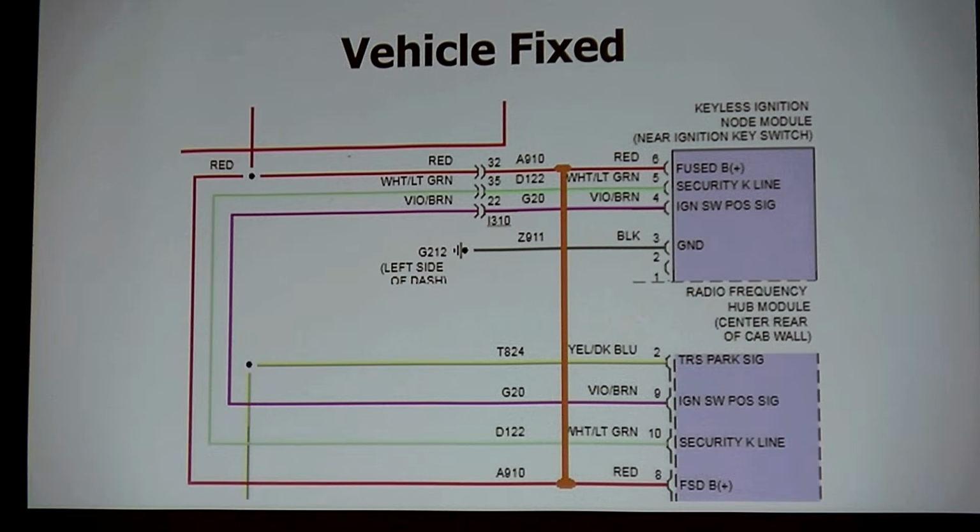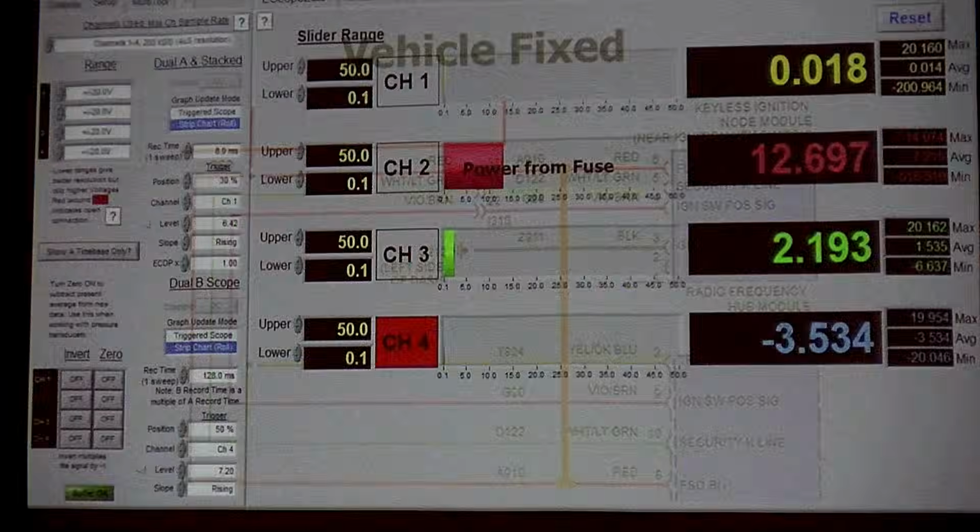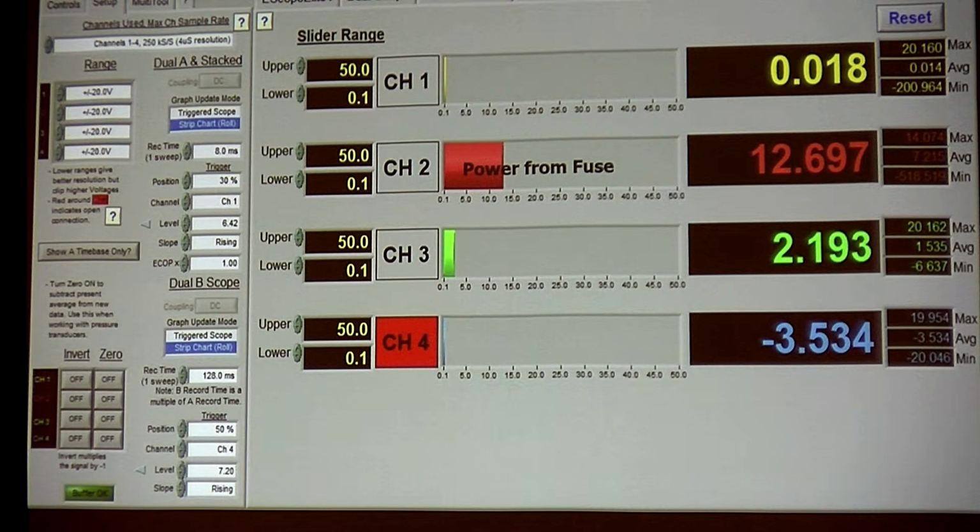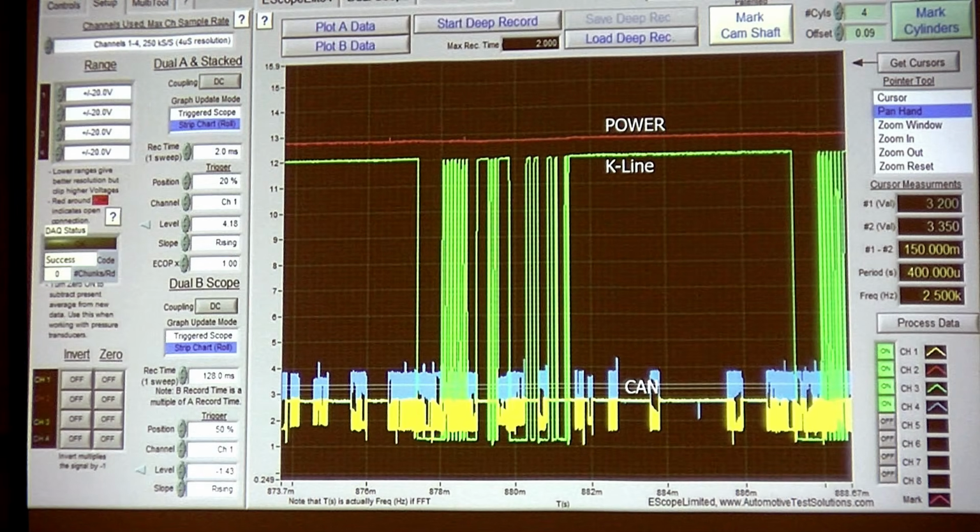All I did is I'm going to bridge that wire right there because I'm in both places right now, right? Just string an outside wire. I'm not wrapping it inside the car. I've got 12 volts now. Look at the K line. Car starts and runs fine. The problem is in a voltage drop situation that goes from the key back to the hub module. This is not hard.